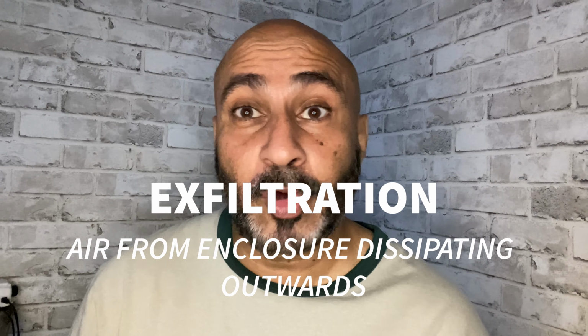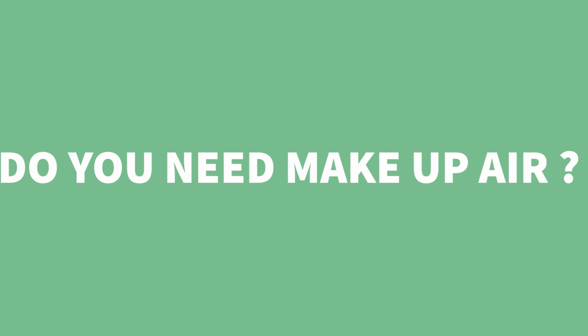And when you install an exhaust fan and you're not going to install makeup air, trust me, we think nothing's going to happen, but that negative pressure in the room is going to create a vacuum and start pulling air from outside. So that is why the terminology of makeup air came about.